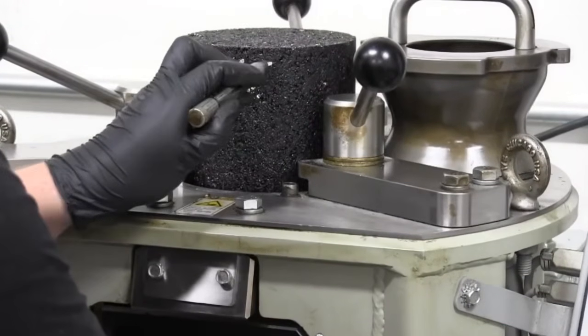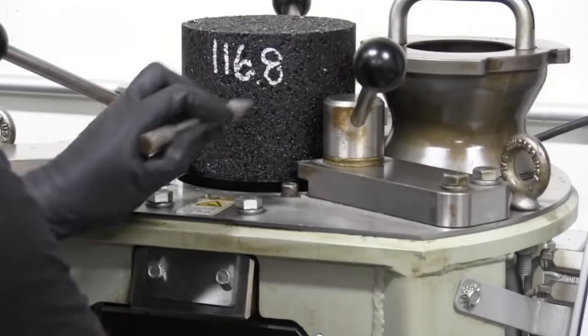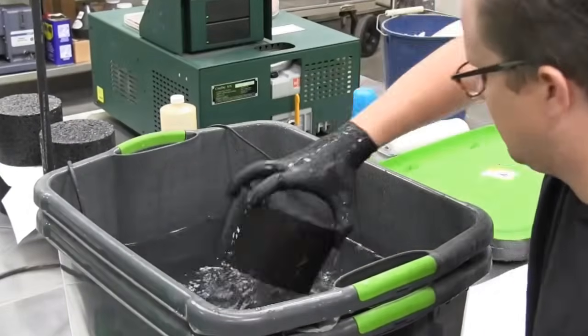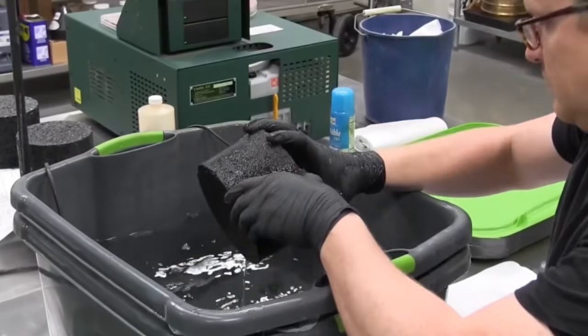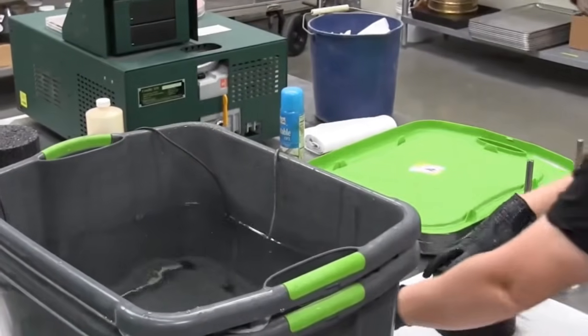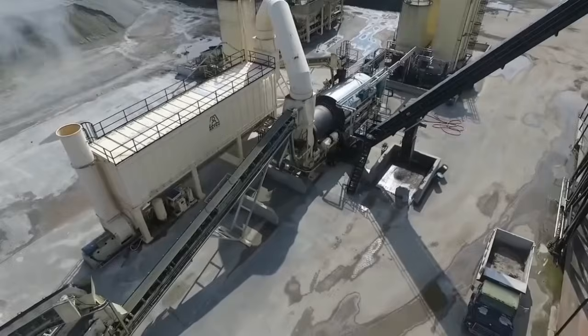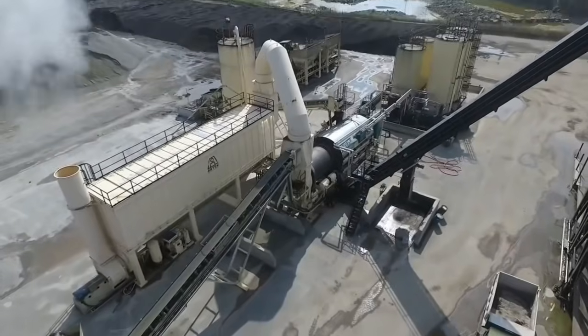Job mix formula shall be prepared and approved by the client before starting the asphalt work. The formula should be within the limit and shall satisfy the quality control criteria as per project specifications. After the job mix formula is approved, the plant trial should be done to confirm the bituminous mix design. Construction procedures to follow are: weather conditions.